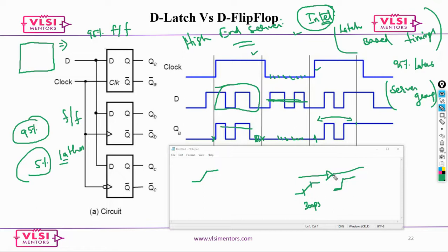Now the output transition, the transition at the output pin, is going to be probably 120 ps. Like this only your transition would get propagated. Now I cannot put that kind of transition things in this picture. We would definitely ask this kind of question in interviews, but not in the written tests. In a written test, it would be tough for you to mark the edges and draw it, whether you need to take it here or take it there. So just learn the concept of what is latch and what is flip flop. That's what I'm looking at.